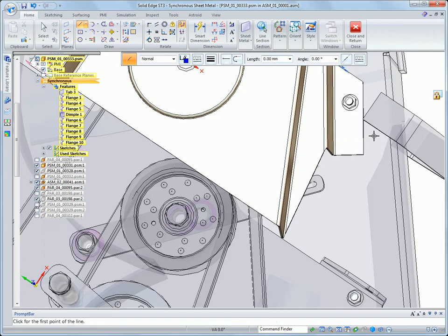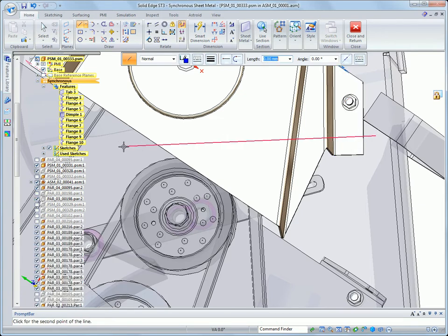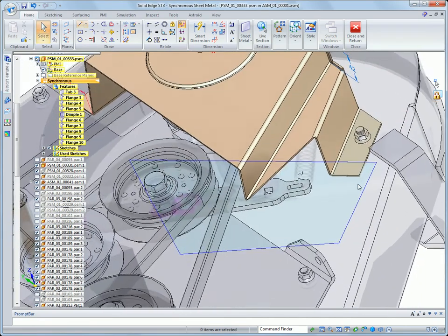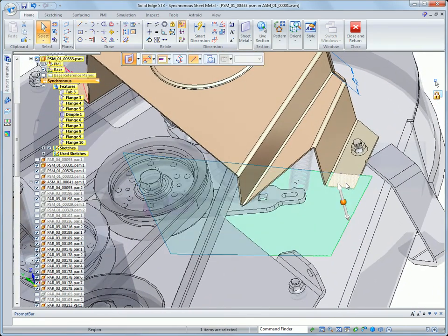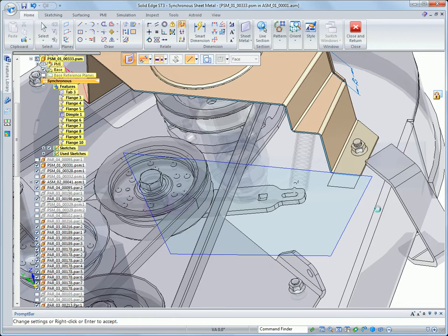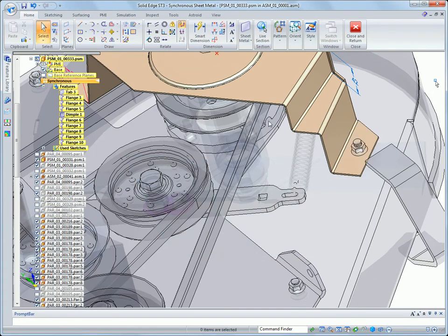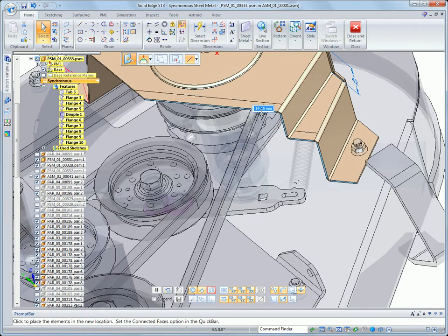When locking to a sketch plane, notice how we can choose which edge we wish to align the X and Y directions to. Creating a closed sketch enables us to drag the interior regions to completely cut through our part to remove unwanted material. Here we're going to use the option for through all. Now we can grab those thickness faces and we can actually adjust this opening in our sheet metal pulley cover.